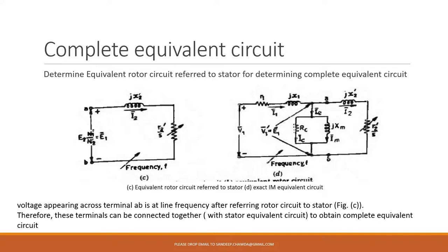See, there is another reason. When you are combining this, the rotor has a different frequency and the stator has a different frequency. So how can you club them? In order to club them, they should be at the same frequency. That's why the rotor parameters are referred to the stator side, and we have obtained the equivalent circuit referred to the stator side.